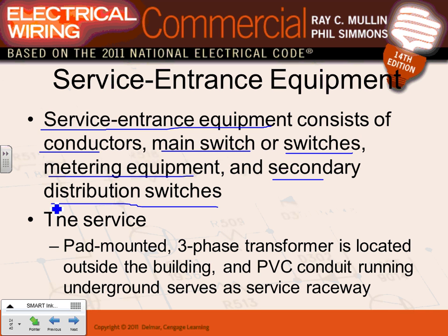Service. We talked about services, guys. Pad mounted transformers located outside the building. This is just for the project that they have. They have PVC conduit that runs underground service, bringing the service from the pad mount transformers inside the building. Typical. You guys did that. You put a transformer outside into a pad mounted CT cabinet. From the CT cabinet, you went inside the building.